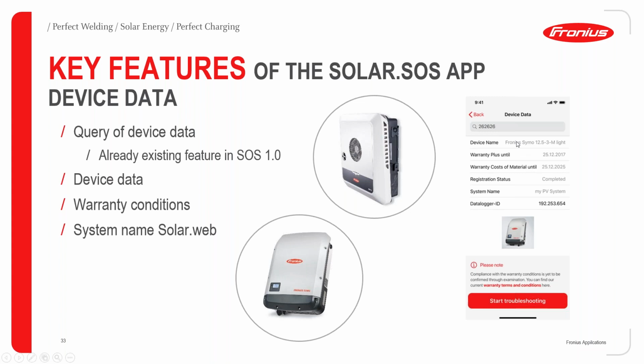As soon as you enter the serial number, you can see on the right hand side the device name. If it is Fronius Light, you already know it is not possible to monitor, or maybe he's a customer who has a data manager box additionally, or maybe he bought it later and retrofitted it. Then you can see the system name here. If it is monitored in the Solar.web, you can find the system name. You can also find the warranty information, how long this warranty plus is, if he has a warranty plus, or if he has only the material warranty, you can find how long he has this.